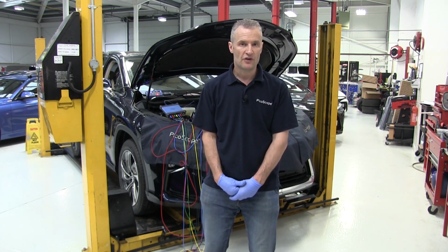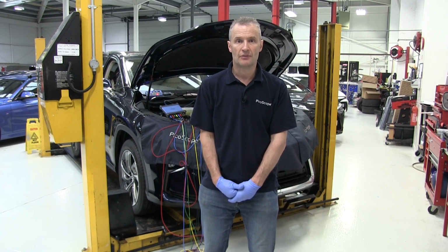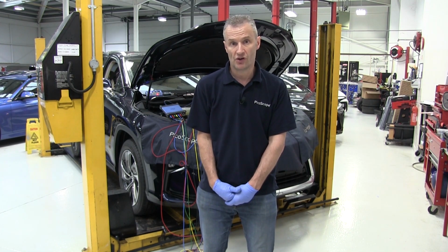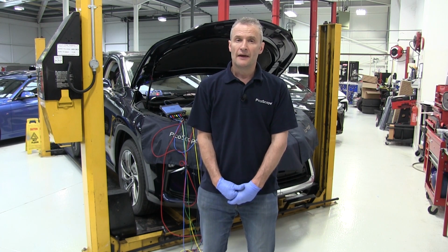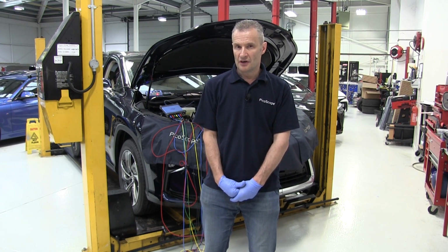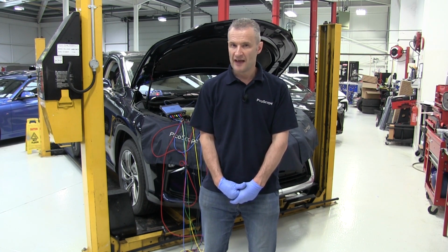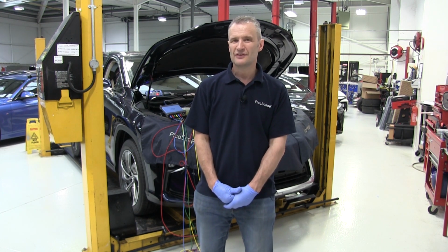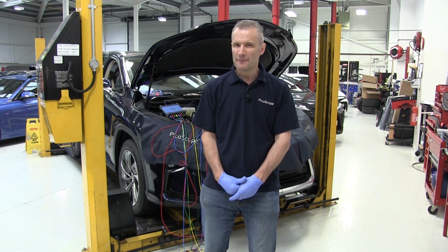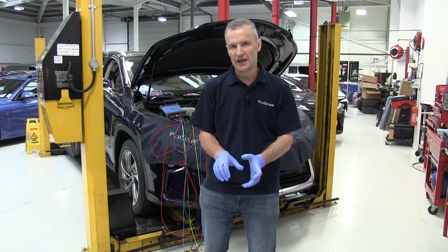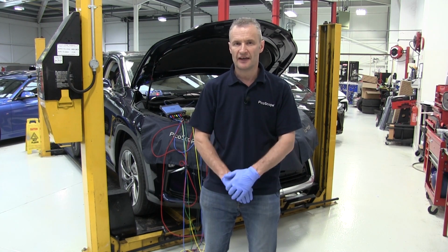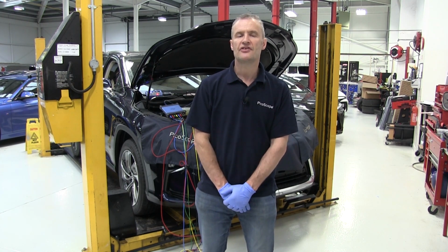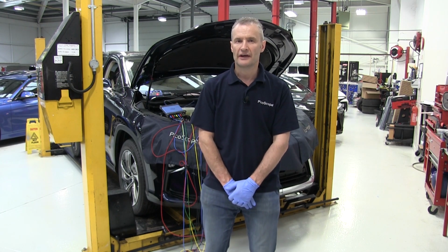It's just that within a few miles of driving the vehicle, a warning light comes on to inform the customer, the driver, that there's a problem. Now, the mechanical inspection of the timing was there or thereabouts. It was a difficult call. Depending on whether you took the slack out of the chain or whether you just eased on the crank a little bit, you could convince yourself that these marks were in line.